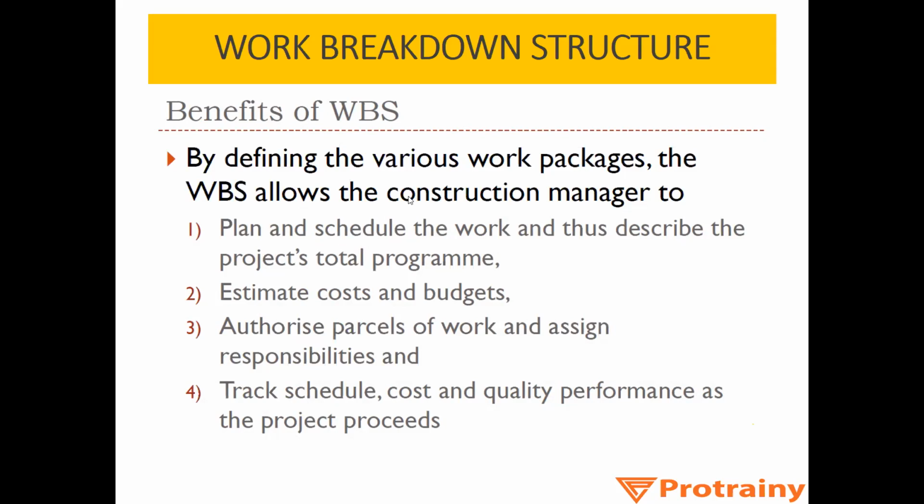By defining the various work packages, the WBS allows the construction manager, first, to plan and schedule the work and thus describe the project's total program. Second, to estimate costs and budgets. Third, to authorize parcels of work and assign responsibilities, so you can easily assign those packages to different people of your team or other contractors, and it is clear whose responsibility each work is.